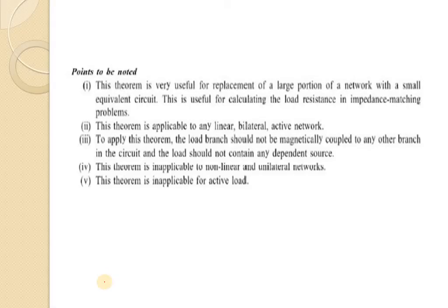Before solving a problem, we have to consider some limitations. Point 1: the theorem is very useful for replacement of a large portion of a network with a small equivalent circuit. This is useful for calculating the load resistance in impedance matching problems. This theorem is applicable for linear, bilateral and active networks.